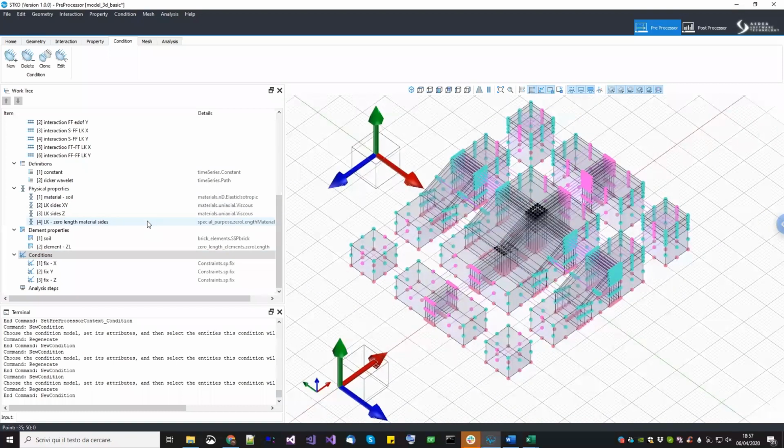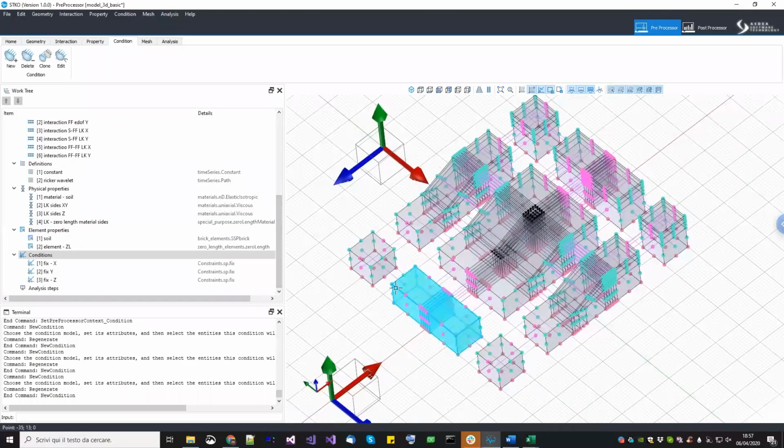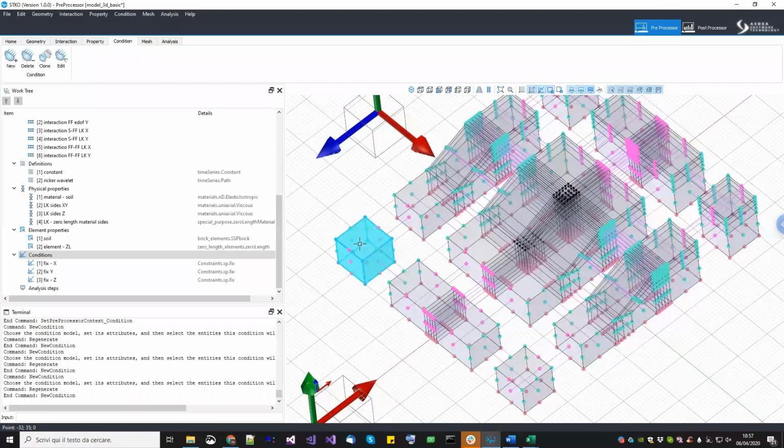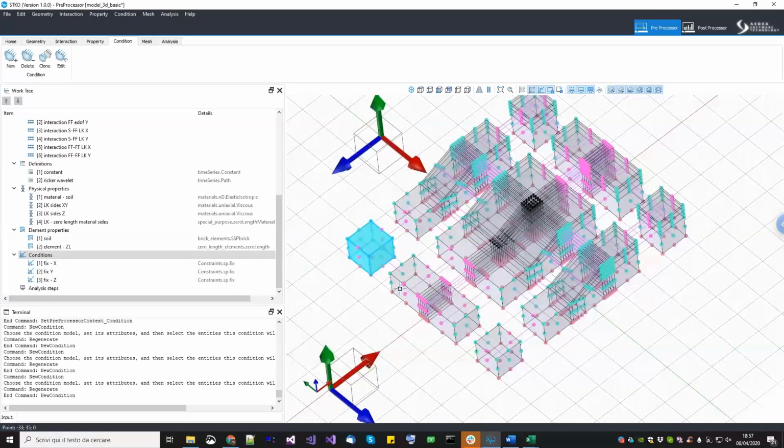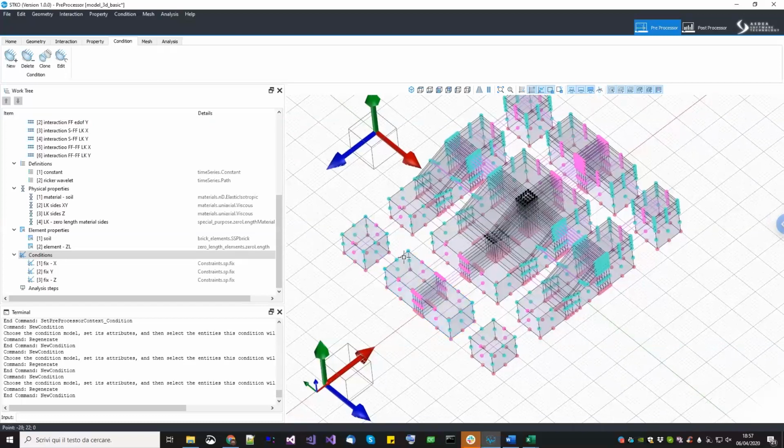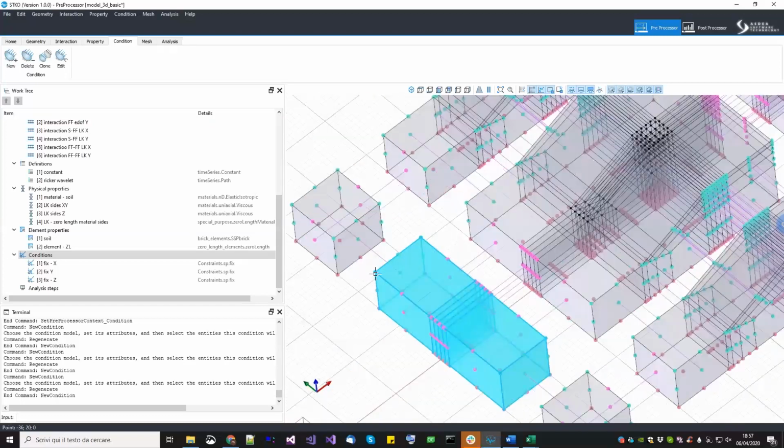Now that we have all these conditions, we need something else. Okay, now the next condition is a kinematic condition for the free field. As I said before, in OpenSees there is not an element for a shear column in the sense that it can only displace in shear. But we can obtain it using a solid element like this and then an equalDOF constraint. Basically, you assign a periodic condition between one side and the other so that they will displace in every direction by the same amount, and in the sense that it cannot stretch or it cannot rotate.